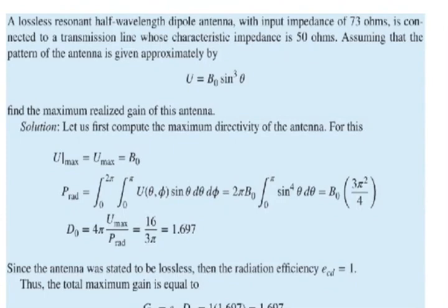It's written here Umax, but it is Um. Then we follow the same procedure. We find the power radiated by this given half wave dipole antenna by making use of this double integration, for limits phi ranging from 0 to 2 pi and theta from 0 to pi, with U the radiation intensity as a function of theta comma phi.